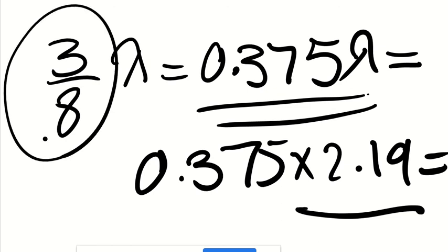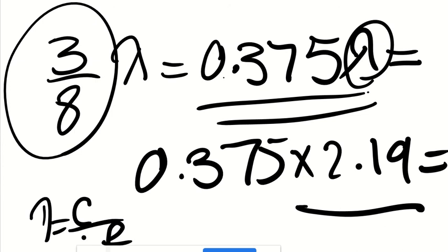This 3/8 is just in the book. It says if I have a transmission line with the length of 3/8 times lambda, which would be a transmission line because it's bigger than 0.1, right? What is the length of the transmission line? So what you have to do is calculate your lambda by doing C/F.